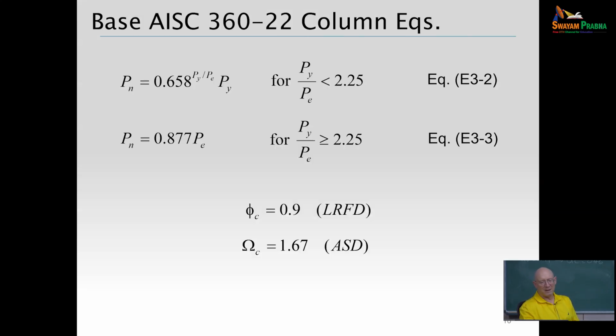And then, okay, let's look at the curves that have been in place since 2005 and even earlier in LRFD for AISC. So this is the form that we've been showing to you, flashing at you a bit. So we have an inelastic strength curve, an elastic buckling strength curve. Elastic buckling strength for AISC is 0.877 of the theoretical.